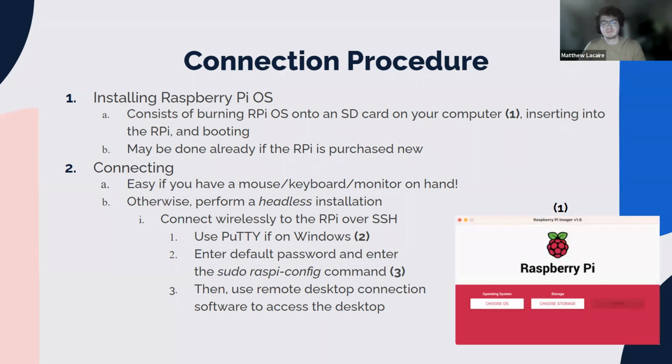So the process in general is one where you get the operating system image, the information for the operating system to establish itself on the Raspberry Pi, and essentially transfer that to the Raspberry Pi. The first step is, on your Windows computer, to get the Raspberry Pi imager, which is shown here, and find some way to connect one of your computer ports to an SD card. There are a bunch of different adapters like that you can find around. Essentially you reformat that SD card and put the Raspberry Pi imager on it. Again, this is all found very easily online.